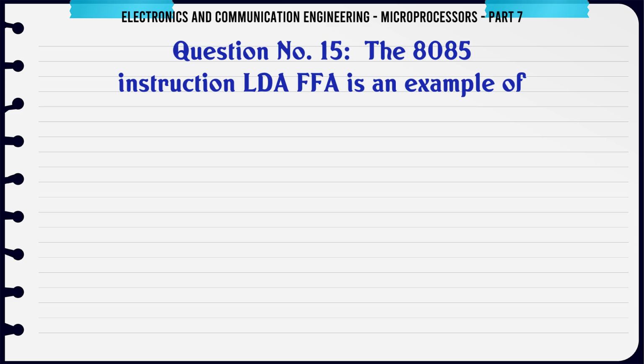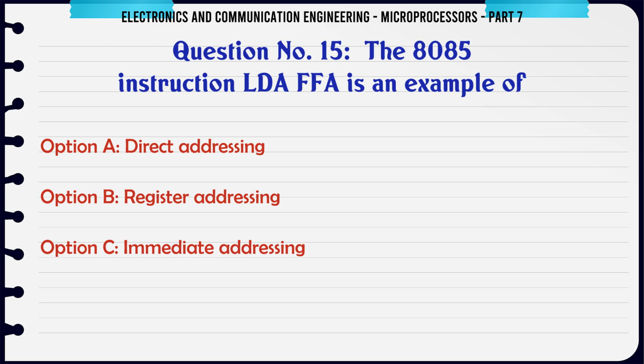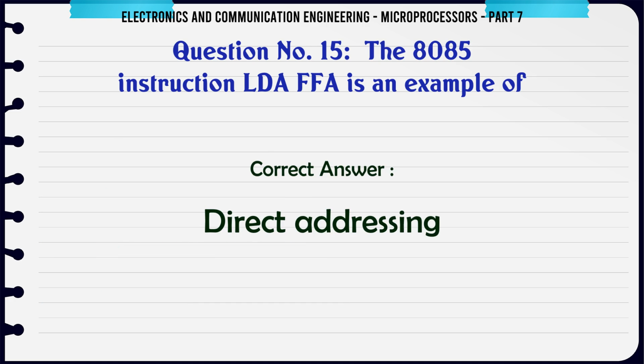The 8085 instruction LDA FFA is an example of: A, direct addressing. B, register addressing. C, immediate addressing. D, register indirect addressing. The correct answer is direct addressing.